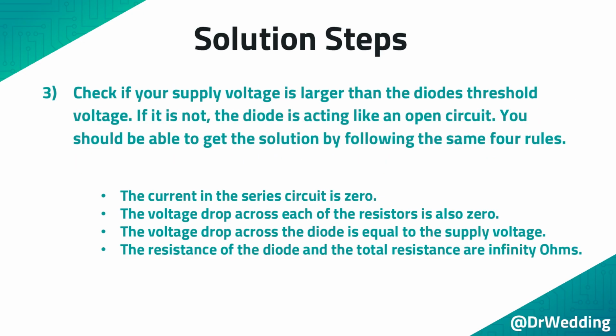Third, check if your supply voltage is larger than the diode's threshold voltage. If it is not, the diode is acting like an open circuit. You should be able to get the solution by following the same 4 rules.